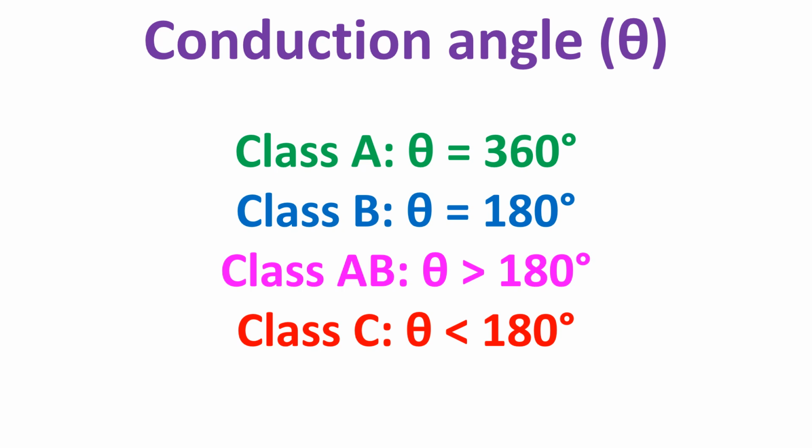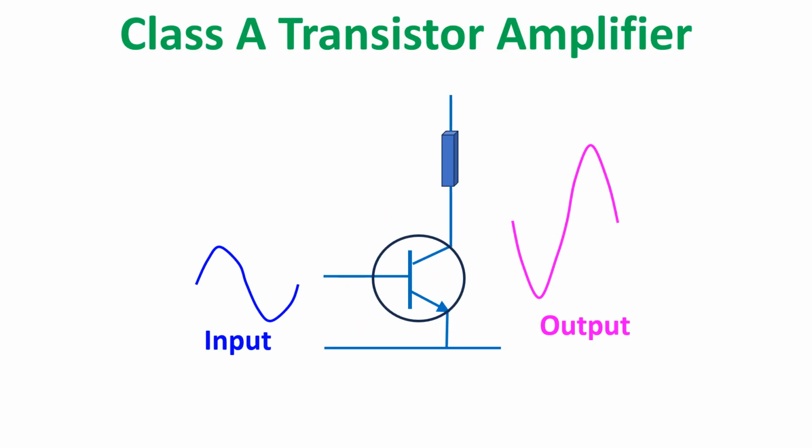Conduction angle has relation to the power efficiency of the amplifier. Transistors biased for Class A amplification drain current continuously and their efficiency is poor. Heat is generated in the transistor. Class A amplifier needs only a single transistor, while Class AB requires two transistors. Bias is in such a way that the transistor operates at the most linear portion of its transconductance curve.